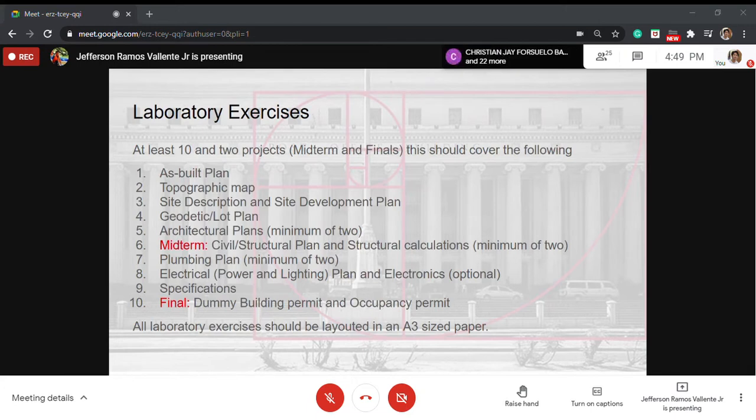So, yeah, the problem was solved, but it would have helped if the client was very transparent in the first place. Yeah, the slope of that terrain is difficult. So if we had been informed ahead of time with the topographic map, we could have better prepared the design. So I encourage you to create a topographic detail or map of your project site.